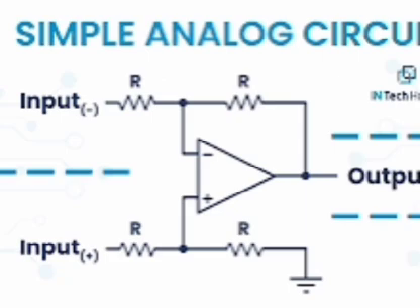Out of the three stability factors, S is the most significant, the reason being that if S is within tolerable limit, then S dash and S double dash are guaranteed to remain within tolerable limit. S ideal equals 1. Practically, S should be less than 20. Alternative evaluation of S equals numerator 1 plus beta, denominator 1 minus beta into dou IB by dou IC. Okay?